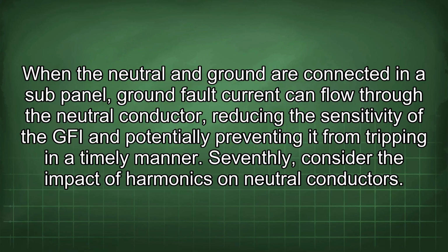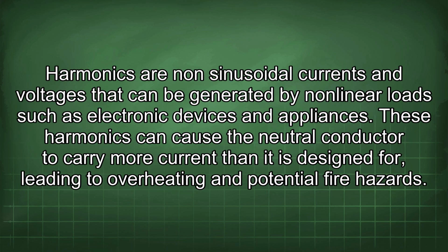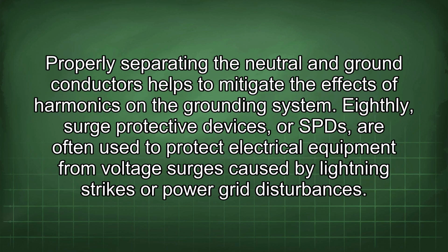Seventhly, consider the impact of harmonics on neutral conductors. Harmonics are non-sinusoidal currents and voltages that can be generated by nonlinear loads such as electronic devices and appliances. These harmonics can cause the neutral conductor to carry more current than it is designed for, leading to overheating and potential fire hazards. Properly separating the neutral and ground conductors helps to mitigate the effects of harmonics on the grounding system.